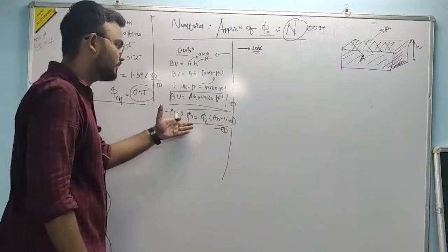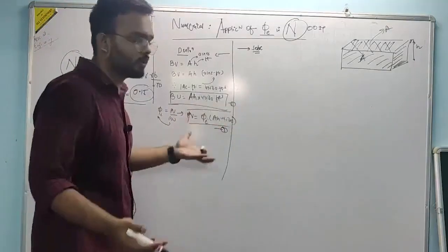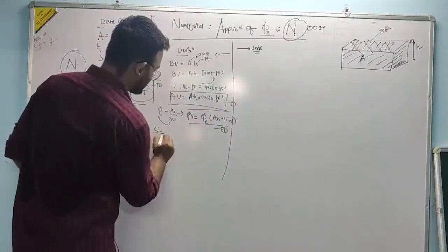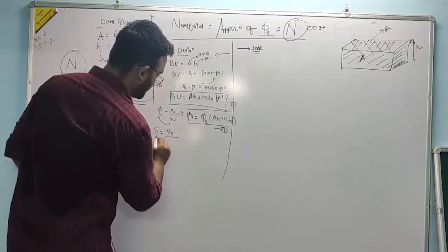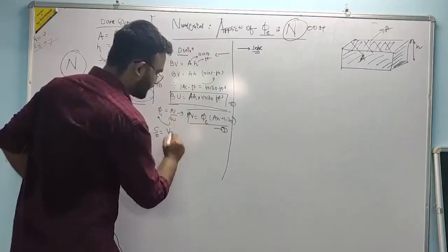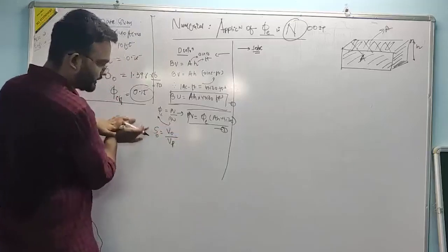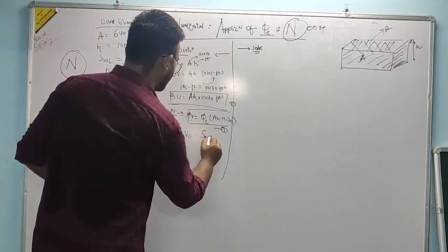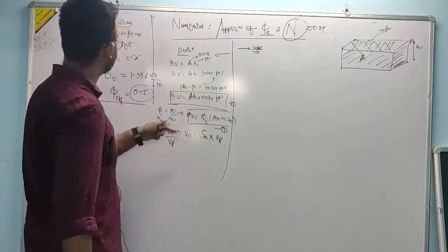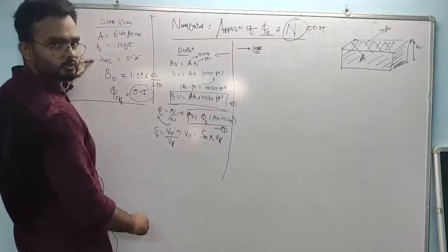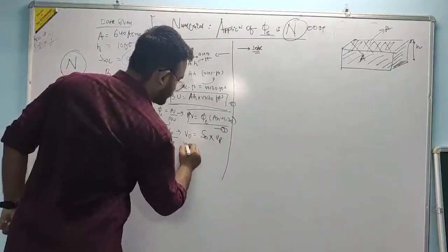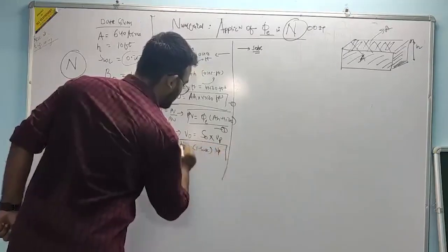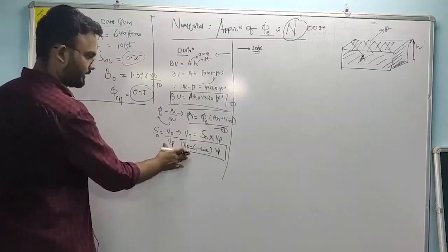Now, in this pore volume, if you multiply by saturation, you'll get the oil volume. Ultimately, that's what our target is. Saturation is volume of oil divided by the volume of pores. This is the pore volume. You can get the volume of oil by multiplying it right here. So the oil volume is S_o times V_p. What's S_o, guys? S_o is 1 minus S_wc, 75%. So 1 minus S_wc times V_p gives you the V_o.